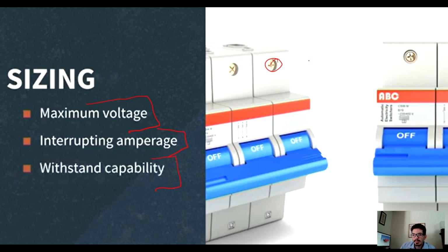So one person will have the responsibility of making sure that there's no power going into the breaker box or the panel board, and the other person will verify that there's no power and will do the swapping, or usually a certified person will do the maintenance or swapping of components. And then when everything is connected properly, the other person would be checking that the connections are okay, and they take out the tag out and bring the panel board back to operation.